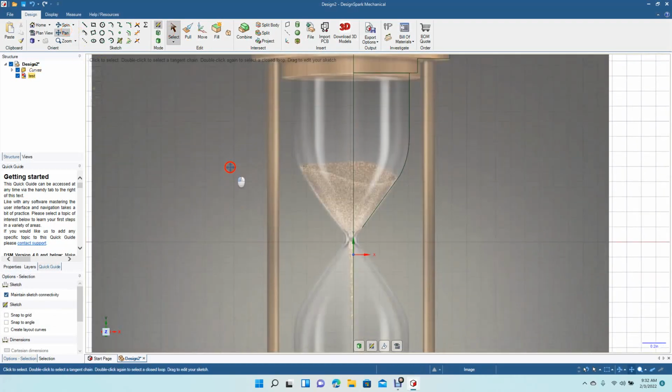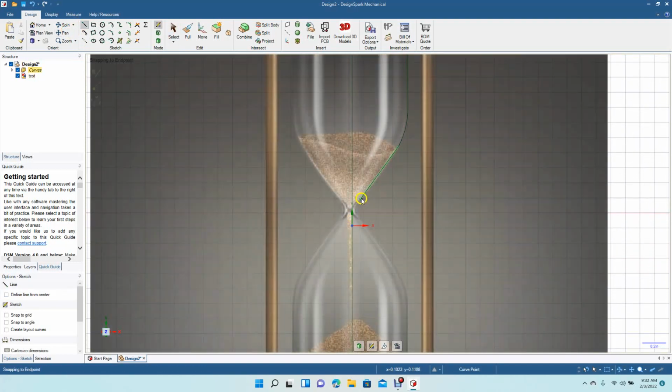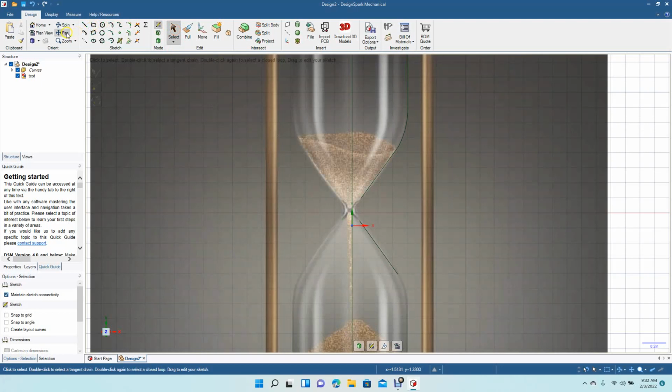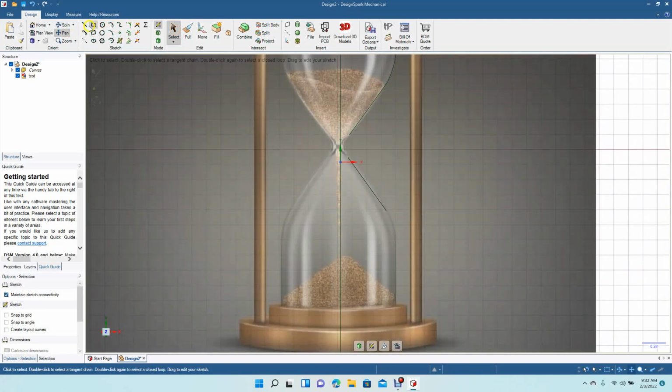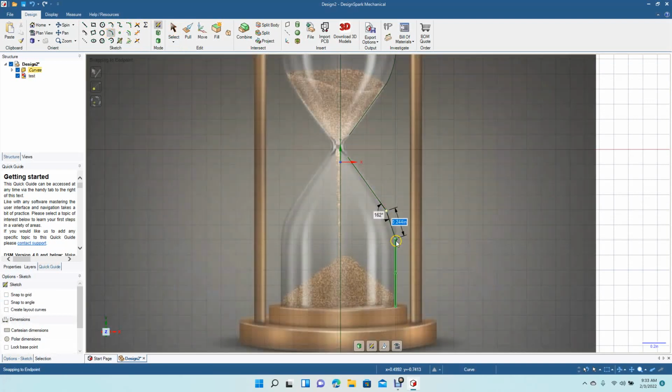Now we want to pan up. And we're going to go ahead and create the bottom part. So we're going to go from here down to here. So we'll click. And then we're going to drag a line out 0.555 inches and 53.4 degree angle. And then we'll select click off. Okay, now we're going to pan up. Now we're going to create this bottom piece. We'll click there, we'll drag up 0.559. Click there, select the click off, grab our 3-point arch, go from there to there.